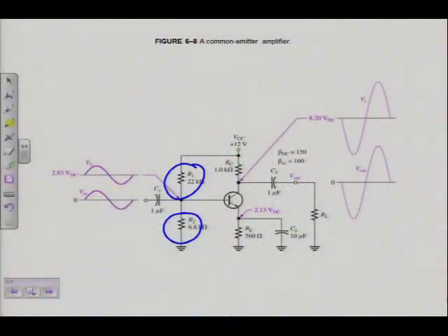Based on the knowledge that you've learned in electronics 1, we've seen then that I'm using voltage divider biasing, right? Voltage divider biasing. There are many other types of biasing that you also discussed, but we will talk about them again later. Alright, so voltage divider biasing, common emitter amplifier. We've established why this is a common emitter amplifier.